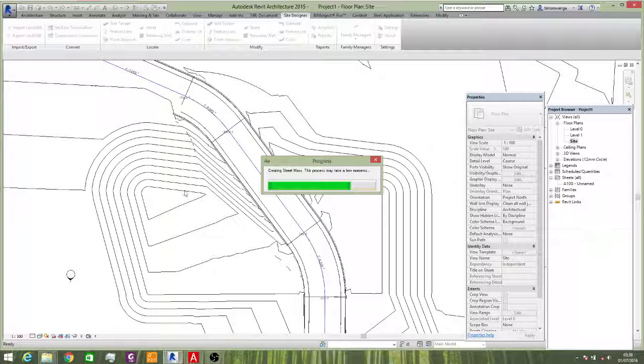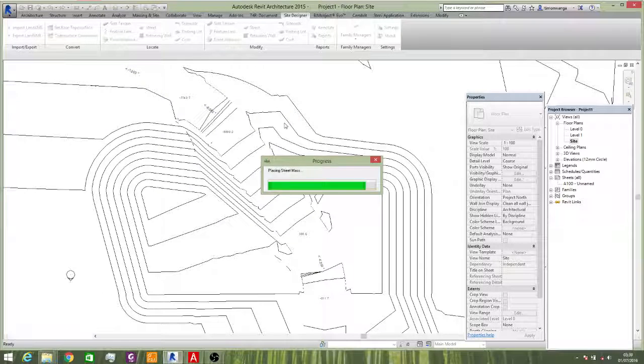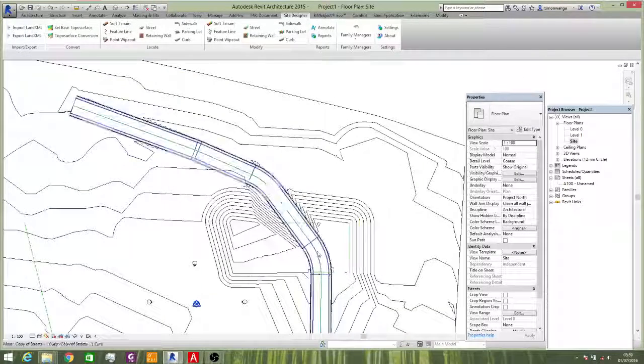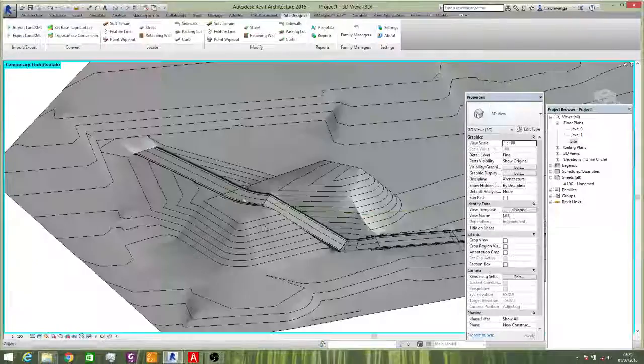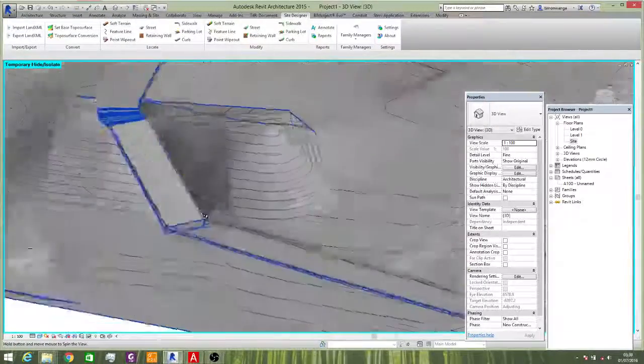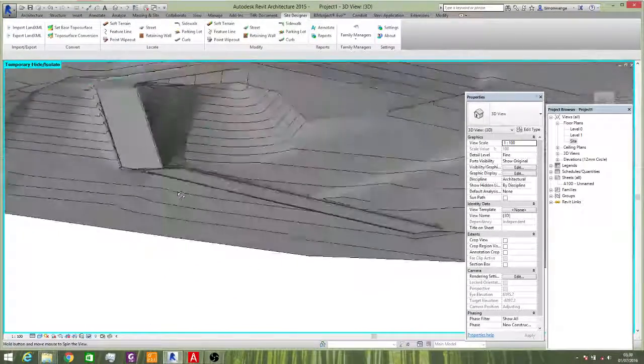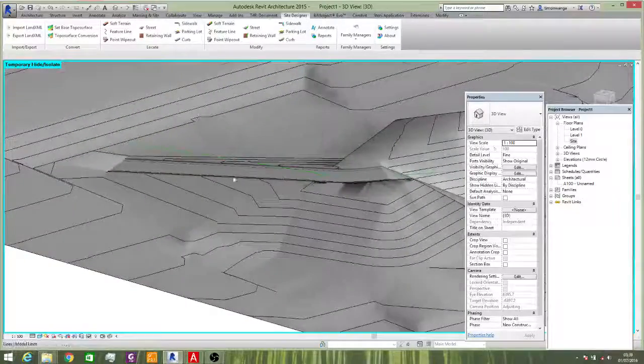While it's doing that, it's important to know that you can actually create more than one road, or even intersecting roads, but the complexity is such that at the point of intersection, the reference line or the reference sketch line should only be a straight line. Now if you intersect a road at such a curve, then REVIT site design won't accept it, and that's another disadvantage. Not as such, but it's realistic.